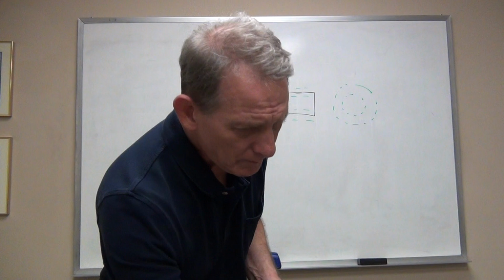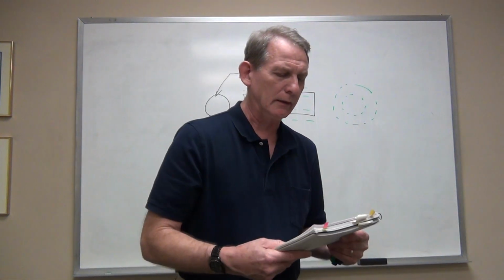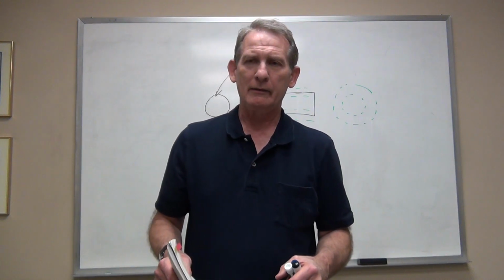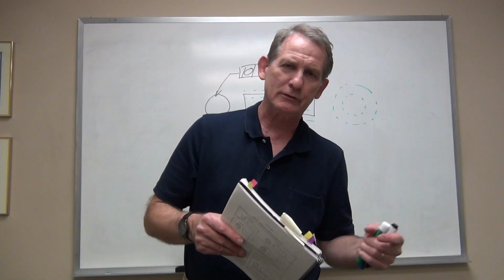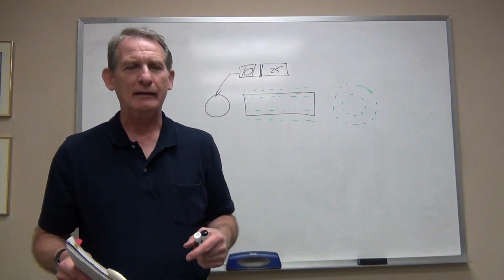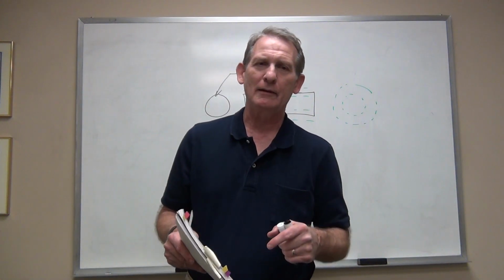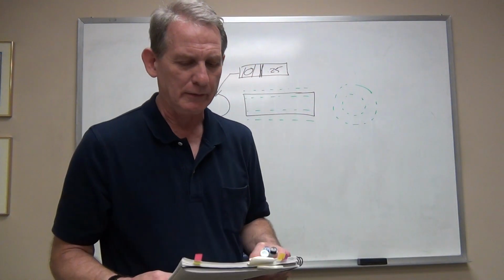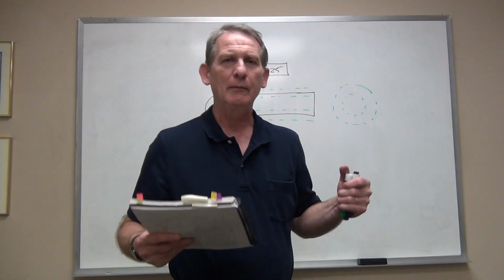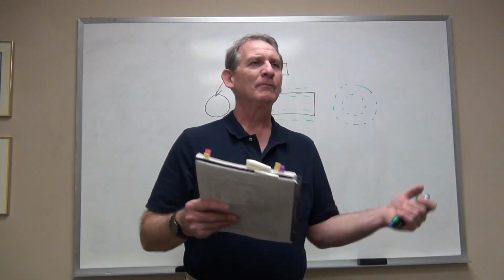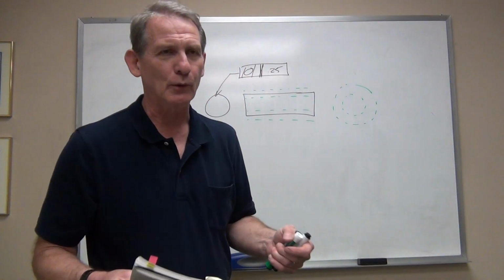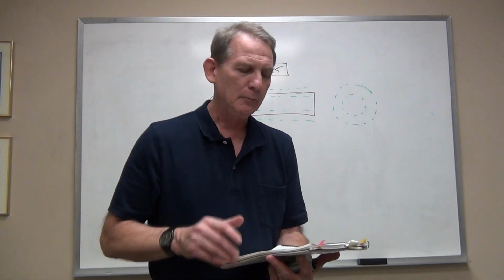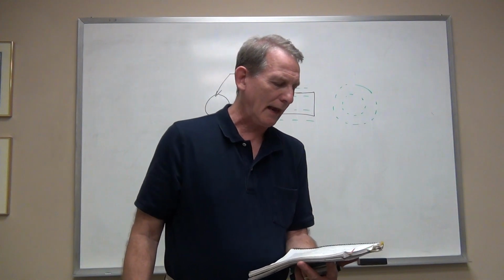This is a control that we can put on a drawing for that very situation that allows a series of measurements to be averaged up. And if you do that in that scenario, you would find that the average would be the size that you would actually cut it to on the part. Now, how many measurements do you use? You get to determine that. More is always better. You get a much closer average as you take more and more readings.